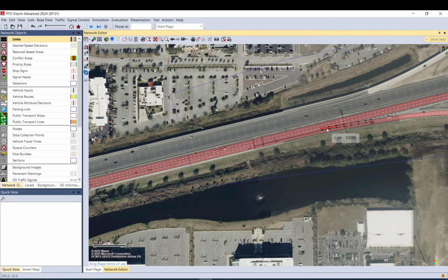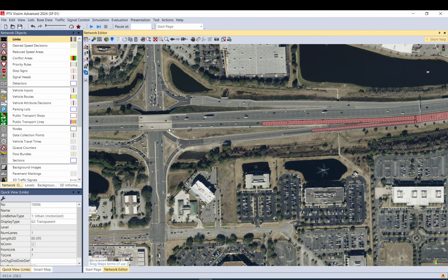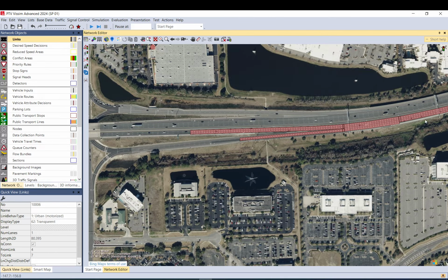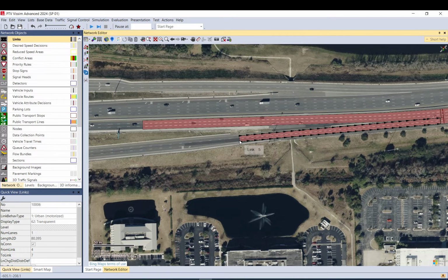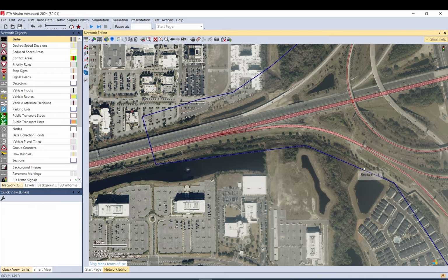Basically, the longer is better, but in some cases, especially if you model an intersection here, the upstream one, you don't want to have it longer than this intersection, because then it can change the flows and cause issues here. If the distance goes beyond that line, the model extent, that's also not helpful. Because if you have a lot of traffic coming here, everyone will start changing lane here, so it will create an artificial, unrealistic, fake queuing.